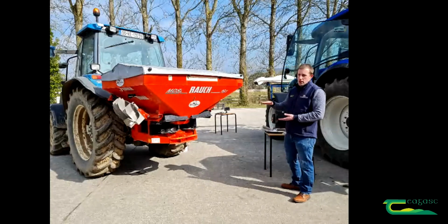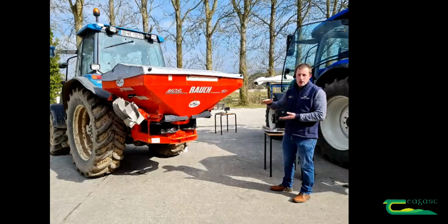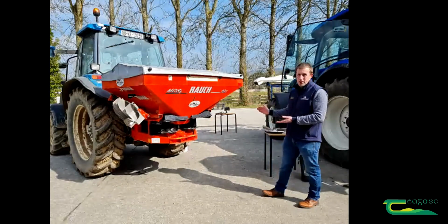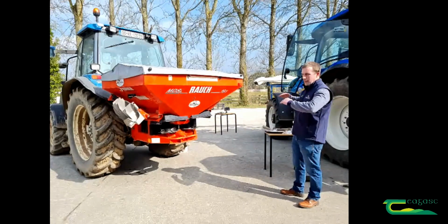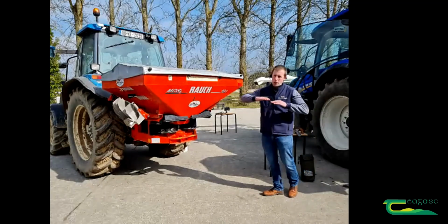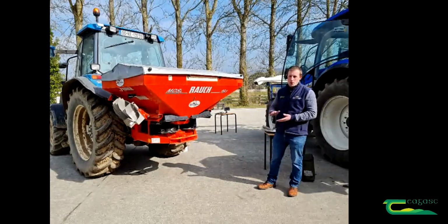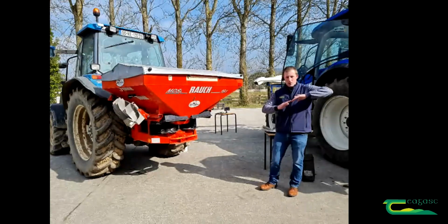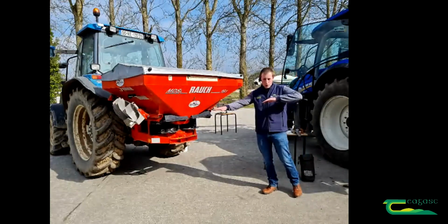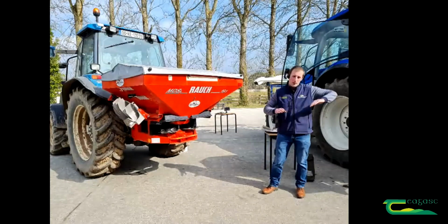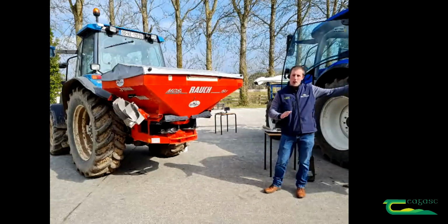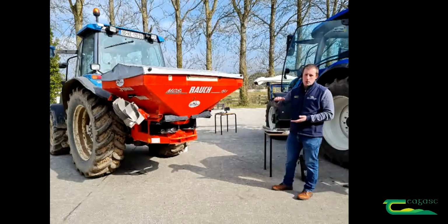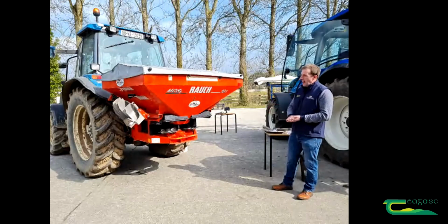Once the height of the machine is set, then it's about adjusting how level your machine is. So essentially you need your machine level left to right. Okay, you don't want it leaning one way or another, because again, if you have it leaning one way or another, that's going to impact on how even your machine spreads. If you can imagine a machine leaning to the right, that disc is throwing fertilizer towards the ground, whereas the other disc is throwing the fertilizer higher into the air. So for that reason, you need your machine as level as possible on left and right.